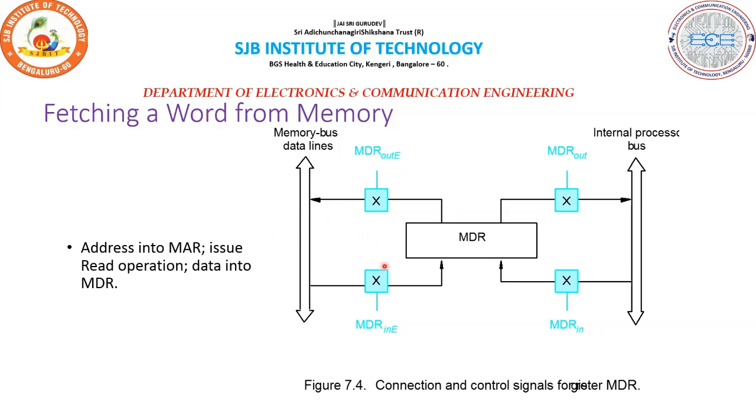A read or write request may be intended for a register in a memory-mapped device. Such IO registers are not cached, so their access always takes a number of clock cycles. To accommodate the variability in response time, the processor waits until it receives an indication that the requested read operation has been completed. The addressed device sets a signal to 1 to indicate that the contents of the specified location have been read and are available on the data lines of the memory bus.